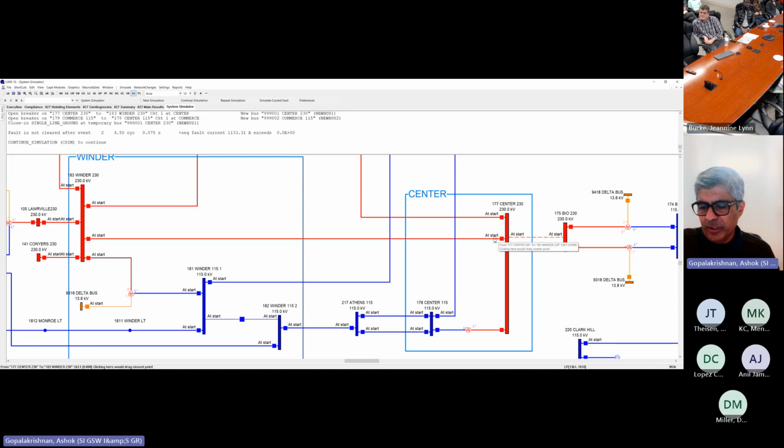That's another important comment. When we're simulating faults, let's say on this 230 kV line, do I need to evaluate relays from everywhere in the system? You don't need to. Once I go maybe 2 or 3 buses away from where I'm located, the relays are not going to be sensitive to the fault condition. So it's a parameter that the user has to set, and we typically set that to around 2 buses, sometimes 3 real buses away, and capture all the protection and simulate that. But that's another point to consider as well.